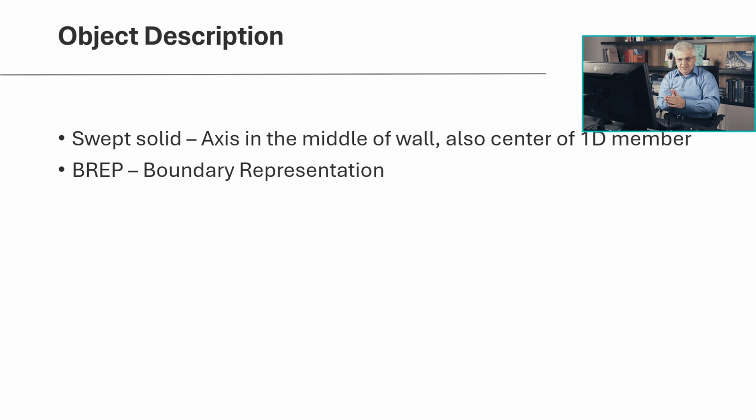Or you can say, I draw the walls on the outside boundary of my building. But during the export to IFC, the middle axis will be exported. So this definition, how the column or wall was created, is forgotten. So everything will be placed on the middle axis.